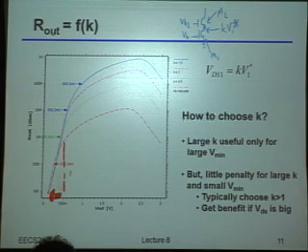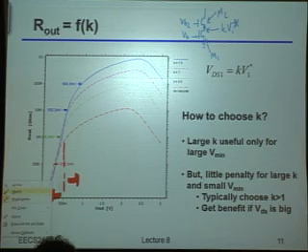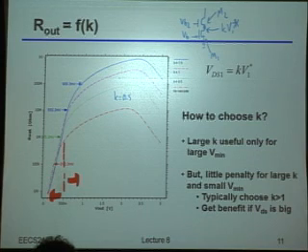But notice once I get above a certain voltage, then you start seeing differences between any cascode at all and the non-cascoded device. Even more than that, and I'll label these because they might be hard to see: this is K of 0.5, this is K of 1, this is K of 1.5.